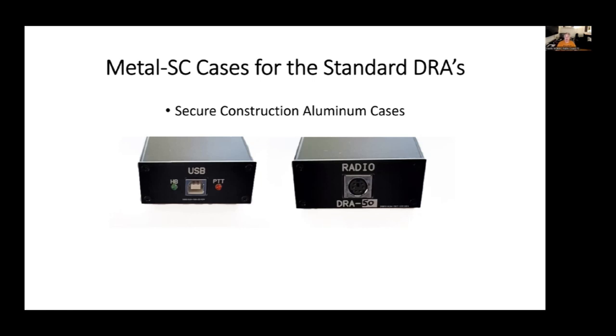They are actually, believe it or not, aluminum printed circuit boards. These end panels are made by the same people that build our boards, but they're aluminum. And everybody's probably going, okay, aluminum circuit boards, how does that work? Aluminum boards are not intended to have through holes. They're only intended for surface mount applications where a device soldered fast to it needs to have a lot of heat taken away.